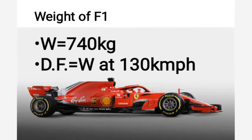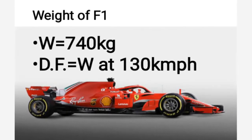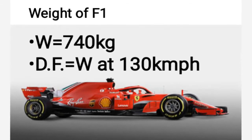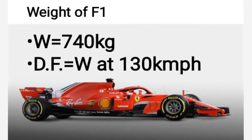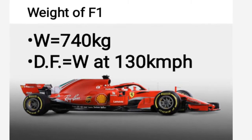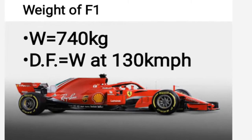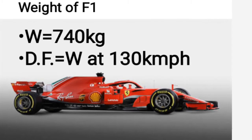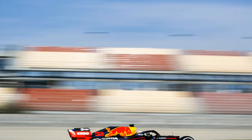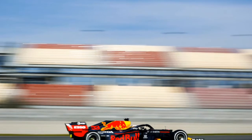Do you know a Formula 1 car weighs around 740 kg and it is able to produce a downforce 3 times its weight, which is 2220 kg, which is 2.22 tons. The car is able to produce a downforce equal to 740 kg, which is equal to the weight of the car, at 130 km per hour. This is why Formula 1 cars are able to take corners at such huge speed.